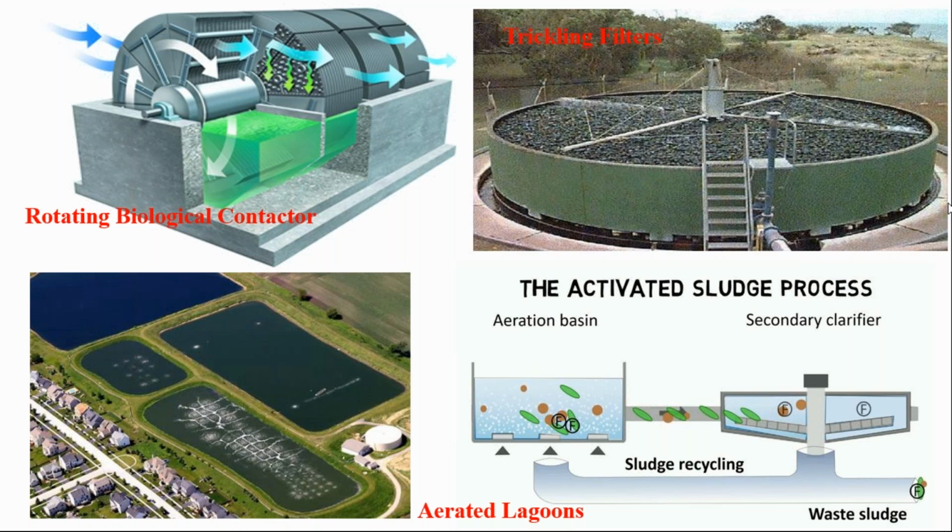You can understand that wastewater can be sent to these different media, that may be a biological membrane, that may be different types of media where the biological treatment can be carried out. And after the treatment, this wastewater can be sent to the next process or the next step. So this is the biological medium which is available in the rotating disc or rotating membranes, and it rotates with the help of motors, and that is why it is called a rotating biological contactor.